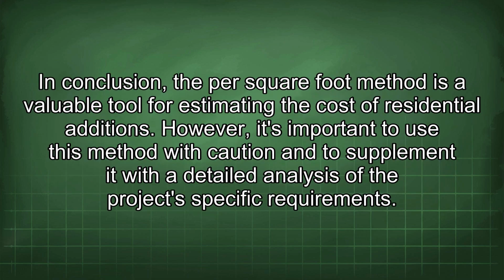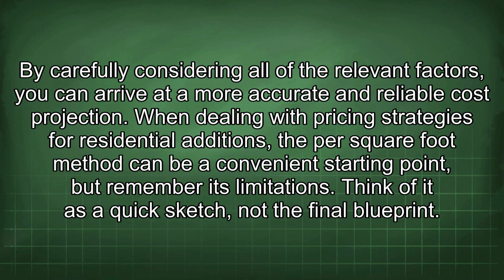In conclusion, the per square foot method is a valuable tool for estimating the cost of residential additions. However, it's important to use this method with caution and to supplement it with a detailed analysis of the project's specific requirements. By carefully considering all of the relevant factors, you can arrive at a more accurate and reliable cost projection. When dealing with pricing strategies for residential additions, the per square foot method can be a convenient starting point, but remember its limitations. Think of it as a quick sketch, not the final blueprint.